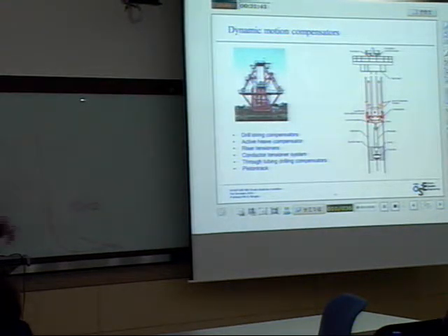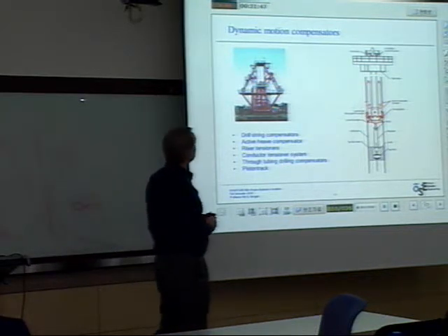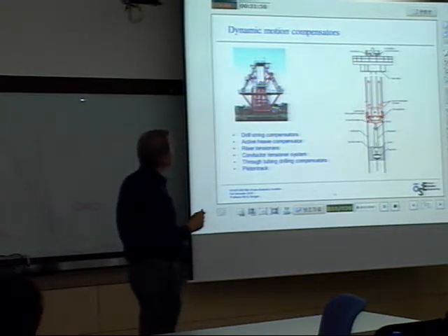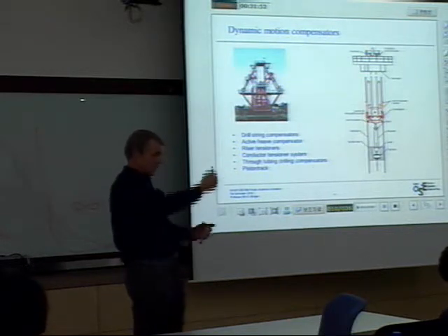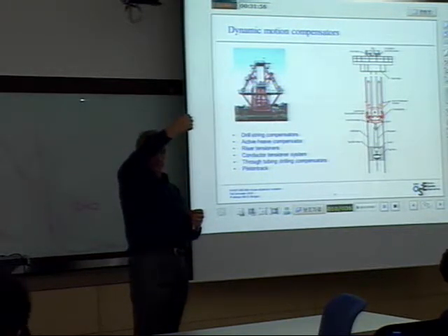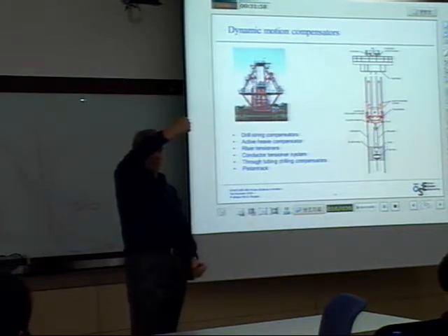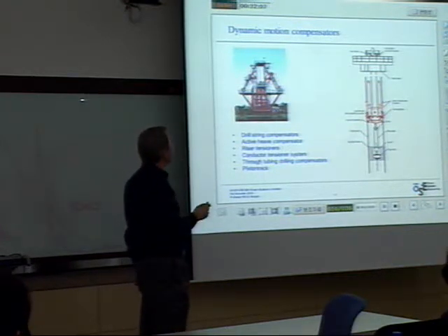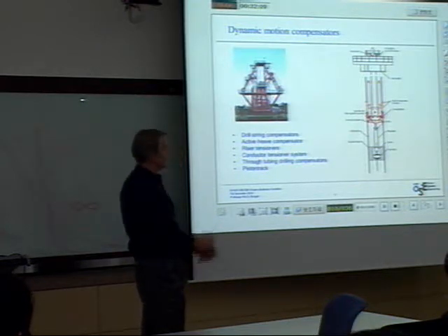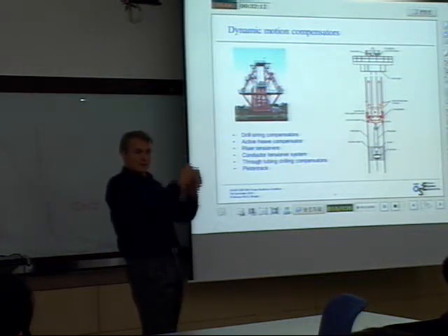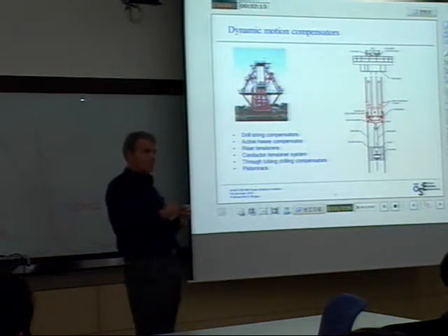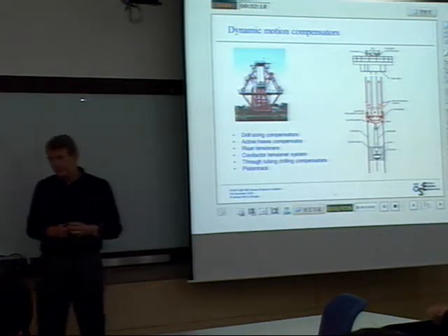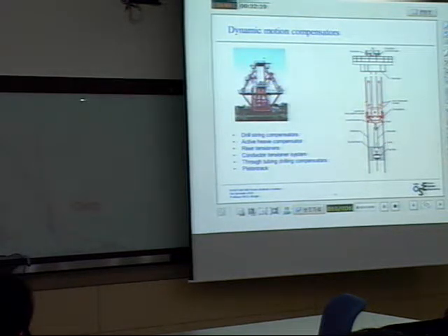And of course, when the platform is moving, you may have to have something called a heave compensator or motion compensator. If you have a pipeline or a conductor from the seafloor and the platform goes up and down, you have to have a more or less constant pull in the pipeline. Then you have a mechanism with a hydraulic system that can pull this up and down in response to keep a constant tension. So again, this technology is not straightforward.